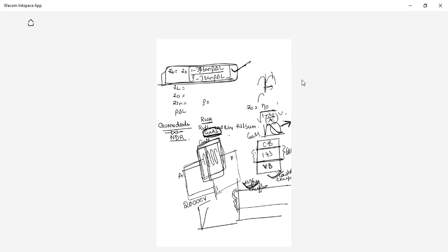Initially, as you apply the voltage, electrons move from the valence band to the conduction band, so the current increases. As you go on increasing the voltage, electrons move from high mobility to low mobility, but since the mobility is low, electron movement is very little, so the current decreases.